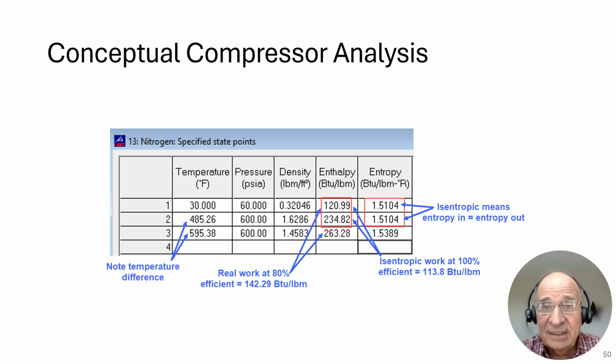In other words, an ideal compressor might require 100 horsepower, but a real world compressor might require 120 horsepower. There's always losses involved. In this particular case, we happen to be dealing with an 80% efficient compressor. So let's take a look at the compressor.